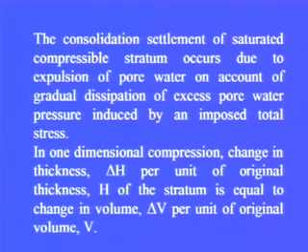Now, as you must have learned in the soil mechanics course, the consolidation settlement of a saturated compressible stratum occurs due to expulsion of pore water on account of gradual dissipation of excess pore water pressure induced by an imposed total stress. In one-dimensional compression, the change in thickness delta H per unit of original thickness H of the stratum is equal to the change in volume delta V per unit of original volume.